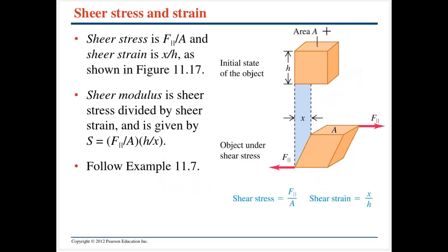Shear stress is fairly similar. Rather than having our forces be perpendicular to the surface, now I'm going to have my forces acting parallel to the surface, and as you would expect, that's going to deform the object kind of like this. Same type of thing, we're going to have a shear modulus, which is a stress divided by a strain.